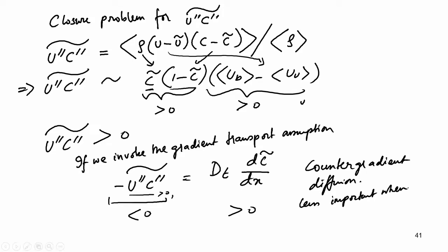And of course, this becomes less important when your u prime is much greater than S_L, that is, when turbulence is very strong, okay. The reason is that counter gradient diffusion considers both things: turbulent mixing as well as gas expansion. When you apply the gradient transport assumption, you consider only turbulent mixing, you use it to model only turbulent mixing. But here gas expansion, because of U_B being greater than U_U, has complicated the picture, okay. That is what has made things more complicated.